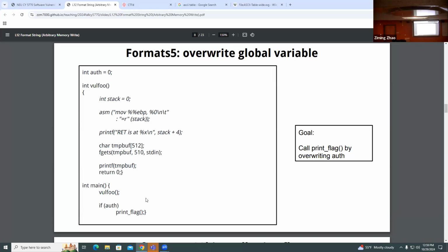So this one, at this point, I don't know what that address is. At a much lower location. So first of all, look at the number. This number is F7FB. So it's probably still on the stack, right? I think a possible explanation, but that's a very small number compared to FF. That's very low. Yeah, compared to FF, it's very low. We can take a look at what that address is.